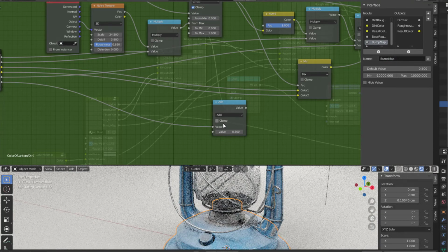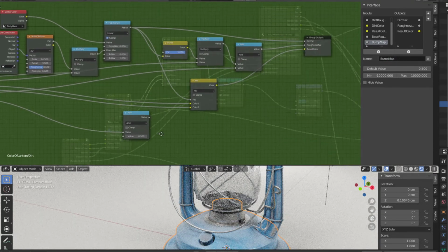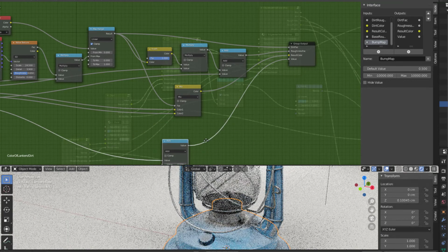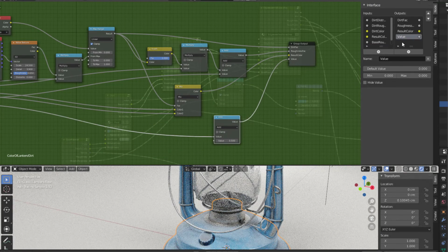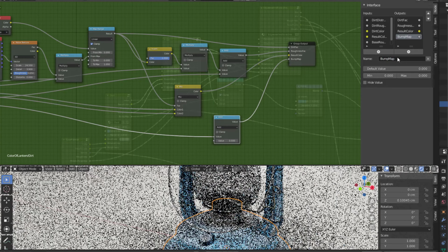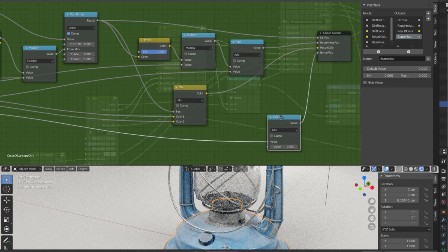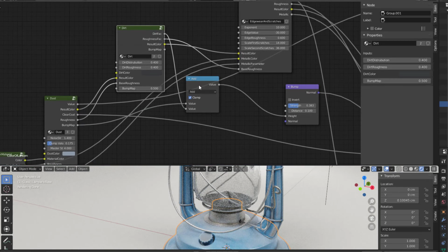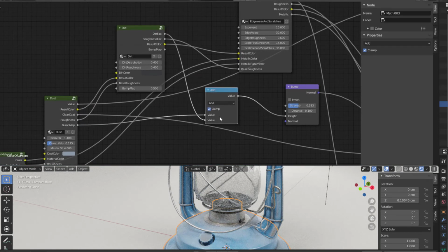So then we have a bump map, and as an output, it will also be a bump map here. So we call that bump map as well. Then we need to add a value here to be certain which of those two I added. I can go to tab. So I come out here, and I take the bump map here and I add it with a dirt factor.